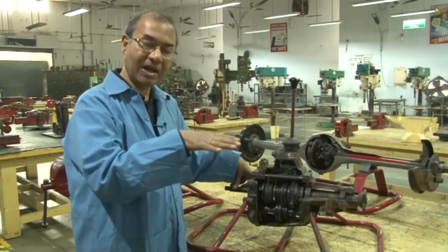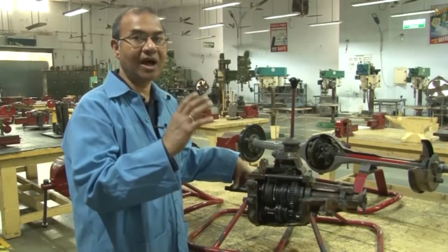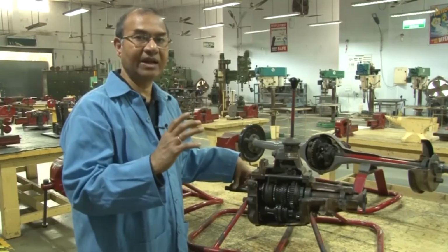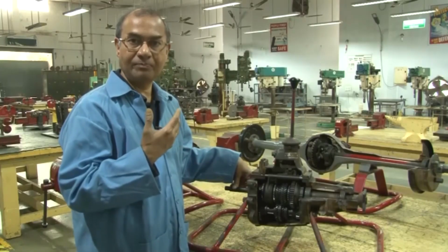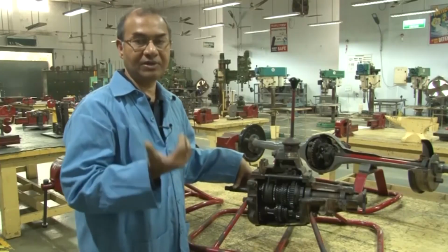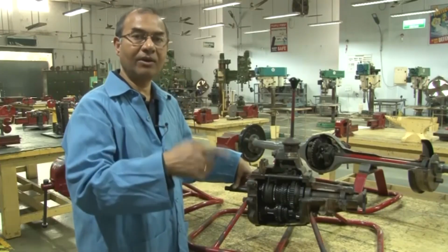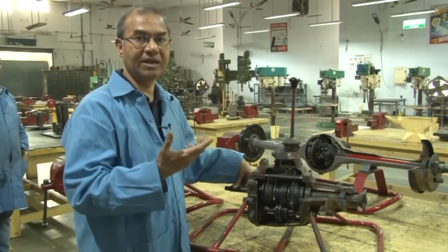But as the car has started going, it already has inertia. So, you do not need the higher torque of the first and second gear, and you will have less torque carrying capacity at the output shaft with respect to the input shaft, and your RPM has to be more, because at 4th gear and 5th gear the car speed is higher.